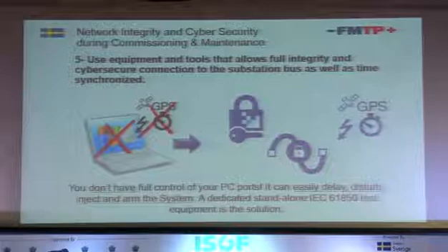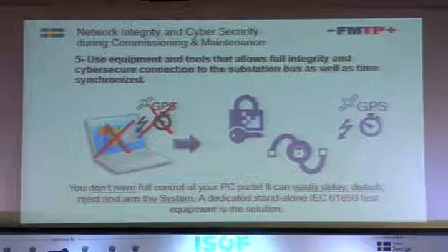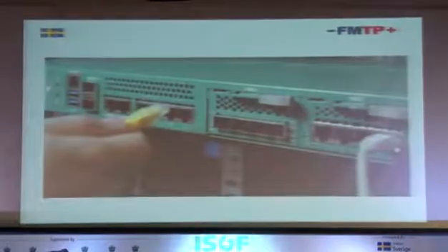Another aspect that is closer to reality in terms of threat. Today and in the past, we have been using laptops and software in order to set up our relays and station, and we can still do that today. But the day you commission the station and put the station live, then the PC becomes a threat. With the PC you don't have control over your Microsoft or iOS operating system. You don't have control of the Ethernet port. So the problem is, do you dare take a PC and connect to a switch in the station, as I saw in this picture here? I will not dare to do that, and I will not do that.